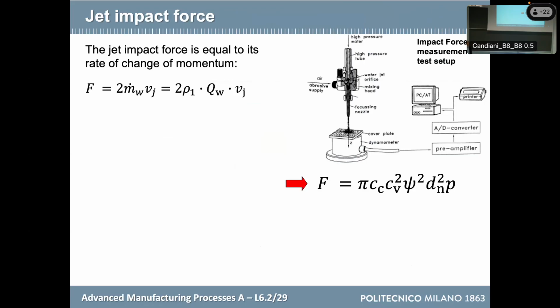It is the pressure. What I do at the beginning of a cut, when the material is fragile, is reducing the pressure. I start, for example, from 200 megapascals. Then I wait a little bit for drilling, for giving the time for drilling. And as soon as the hole has been done, I can increase the pressure and I can go ahead. Because when the hole has been done, then the jet will be really delicate in creating the cutting curve. I can cut almost everything, even carbon fiber or whatever fiber, because it is really delicate, because one grain at a time will do the job.